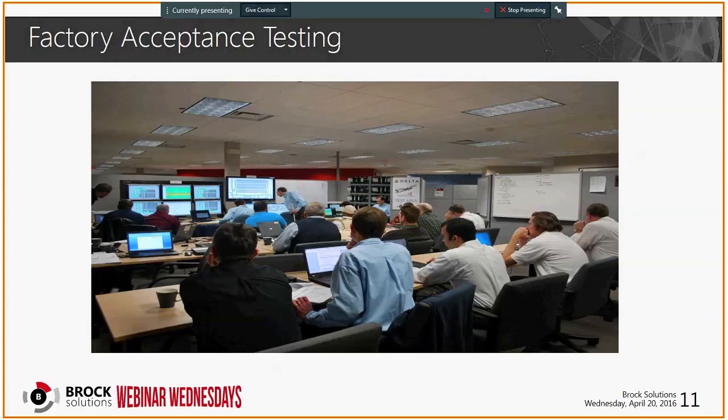After the integrated testing is complete, it's a good idea for the customer to go to the actual facility where the application is being developed, whether it's a system integrator or your software provider that's doing it for you, and take part in a fully functional factory acceptance test. Typically, a core team of people from the customer would go to the site and take part in this. But it's a really great idea, and we found it to be a best practice, to send some operators as well.